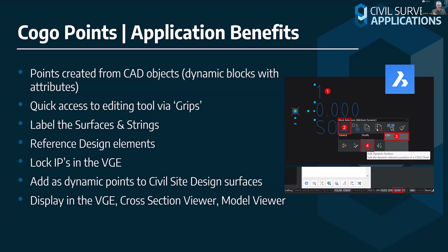But if you want to get access to those same tools, you can use something called the quad, which as you can see there is down the bottom right-hand corner of your BricsCAD environment. And if you turn that on, you'll get access to a series of different options and contextual tools related to the object that you're picking. Have a look at the quad, even just in BricsCAD terms, to see how that works.